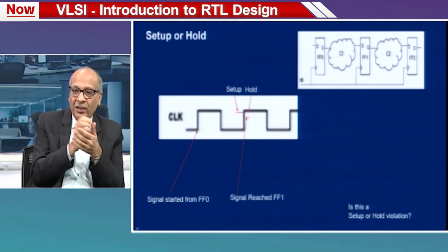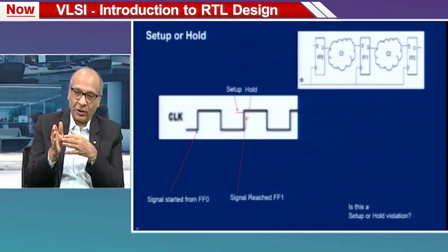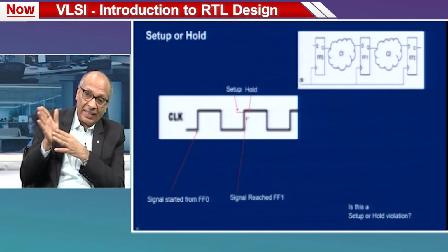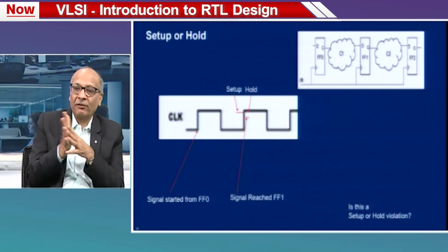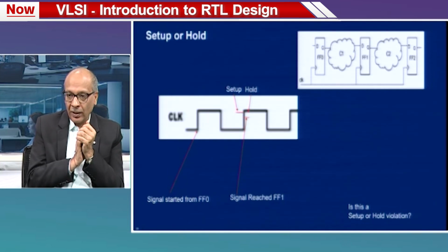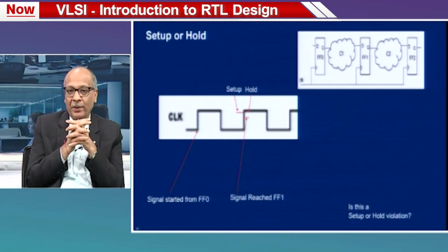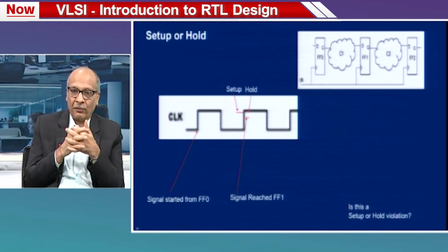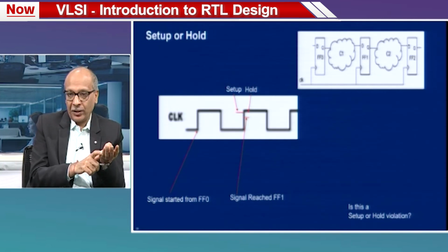For simulation, it is a hold violation because it reached just after the clock edge. If it was further delayed, simulation would not give any violation, while STA would still give a setup violation, right. So, this is another reason why STA based techniques are much more popular. First of all, it does not depend on vectors. Secondly, it can model on chip variation, and third, it ensures that the data should have reached in time rather than it should not have reached at some other time. Okay.